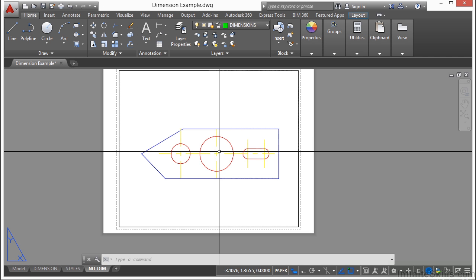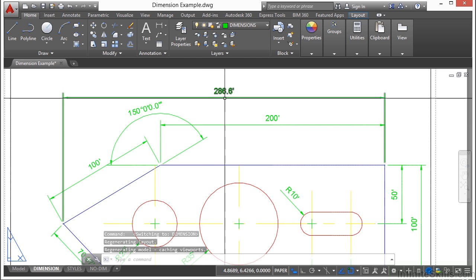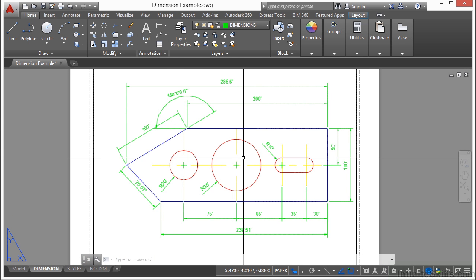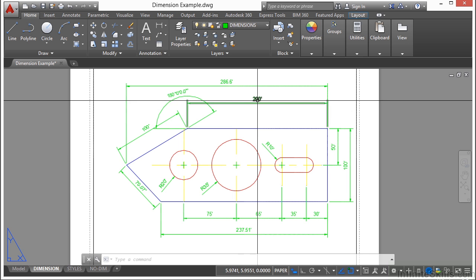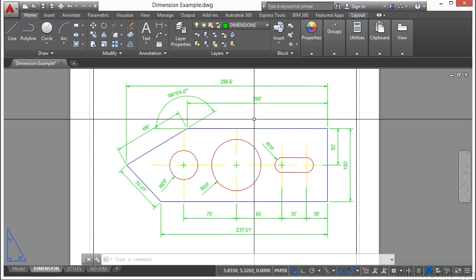You can create dimensions for a variety of object types in many orientations. Linear dimensions can be horizontal, vertical, aligned, rotated, a baseline, or a continued or chained string of dimensions. Here we have several dimensions on this bracket. Dimensions can also be associative, non-associative, or exploded. Associative dimensions adjust to changes in the geometric objects that we measure. I recommend that you always use associated dimensions, especially if you're placing your dimensions in paper space, as is the example here. Dimension associativity defines the relationship between your objects and their dimensions.